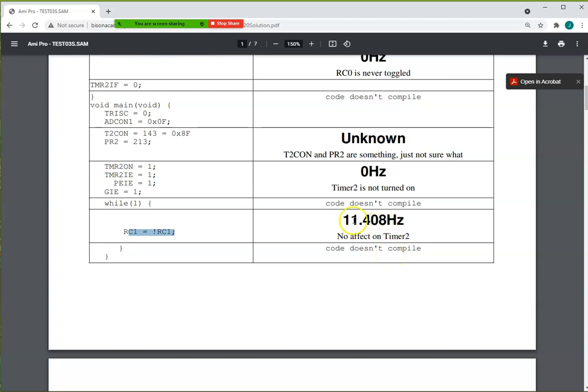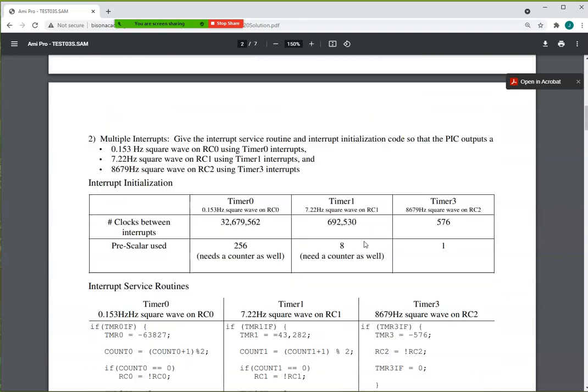This is the same. That's one of the powers of interrupts. Do whatever you want in the main routine. Drive the LCD display, read the push buttons, whatever you want. That's not going to affect this frequency. So that's one problem, just having a single interrupt working.